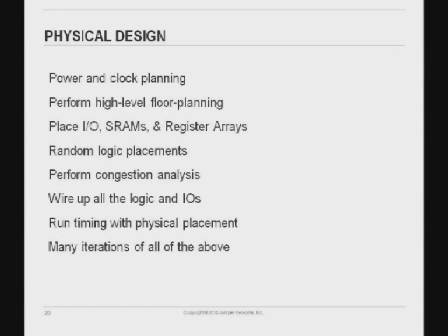So we perform floor planning to see where the logic should be placed. And then we place all the IOs, the input and output, and all the big SRAMs on die in their specific places. And these are usually done by hand, not by tools, because we understand how the logic flows, how the data flows, and all that. And we place them by hand, and after that, we place what we call the random logic, which is synthesized logic, usually by tools. And then we perform congestion analysis before we wire the wires up.